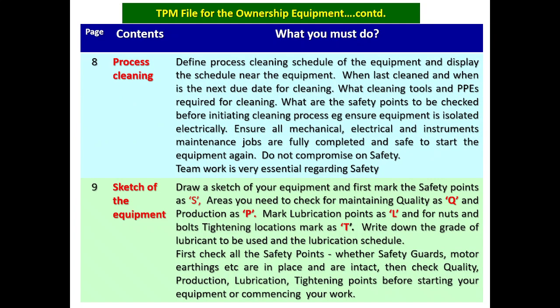Process cleaning is very important. Many industries neglect this point. Prepare a process cleaning schedule of the equipment with the help of your area manager and display the schedule near the equipment, and this should be strictly adhered to. It should contain information like when last cleaned and when is the next due date for cleaning, what cleaning tools and PPEs to be used for cleaning,